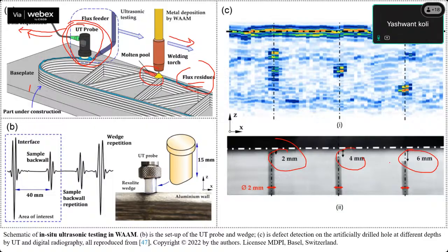The other thing is the X-ray fluorescence spectrometer, XRF, which we can use, and that is also a good thing. It detects changes in wire element composition during WAM fabrication. It uses an X-ray tube, semiconductor based detectors, and a laser profilometer to analyze bead size and element fluctuation. So these things we can use to detect these changes.